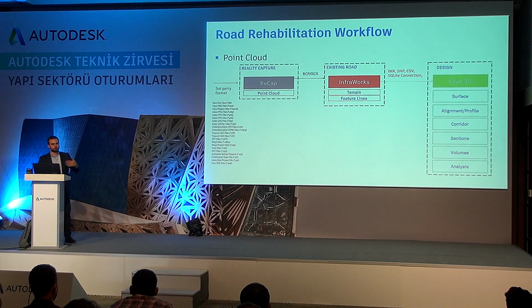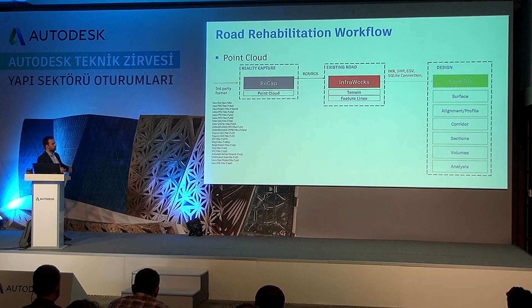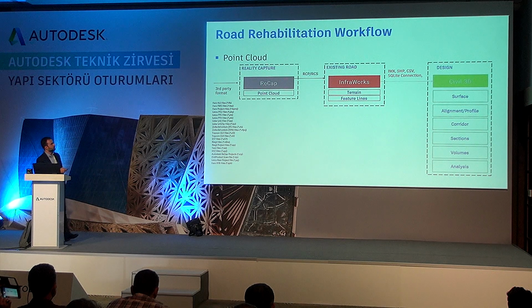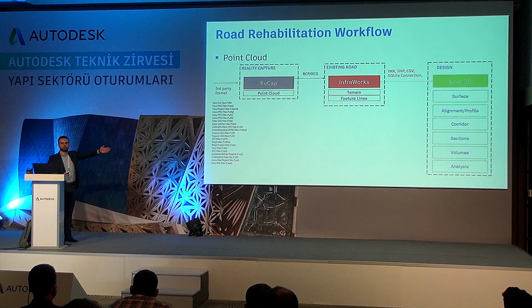The point cloud workflow, the laser scan workflow, allows us to do as such. So remember when I told you about the different providers or manufacturers of laser scans? It could be Faro, Leica, Topcon, and many others. They export the data from the laser scanner in file formats. That data, we use Autodesk ReCap to read it and to register it, because think of a 10-kilometer road.